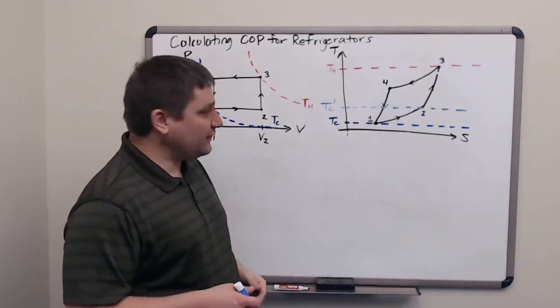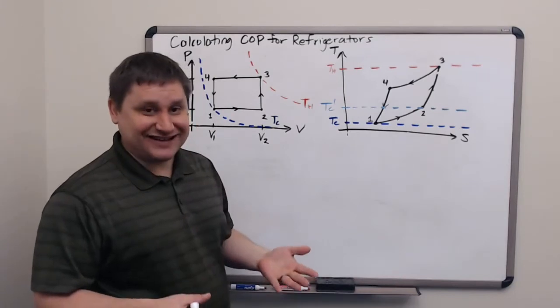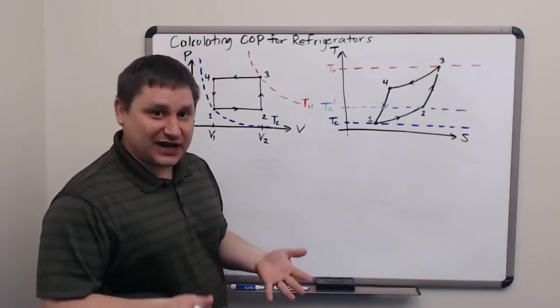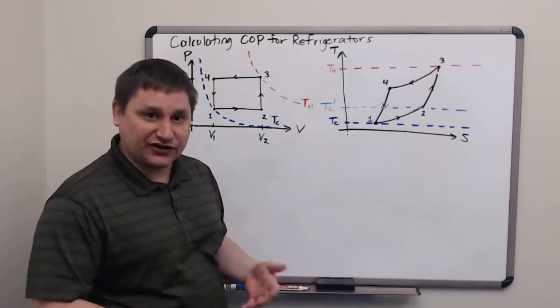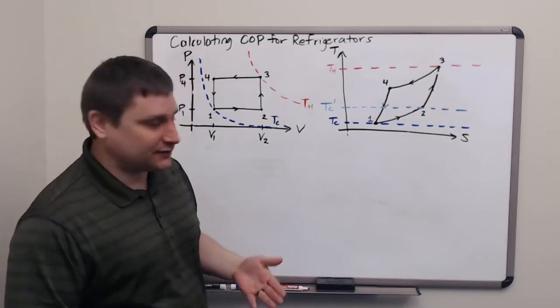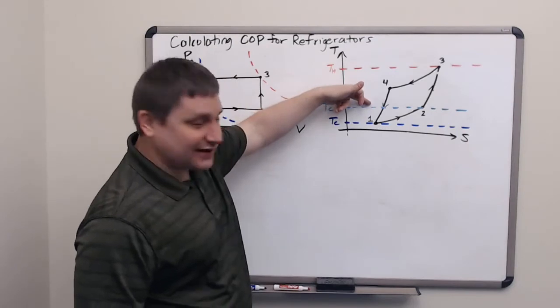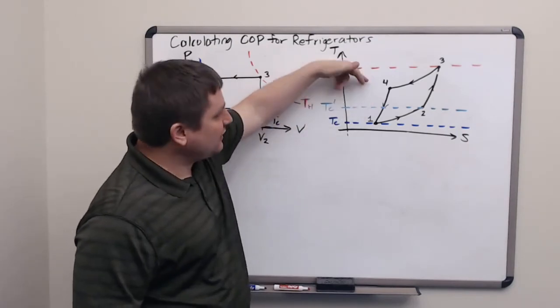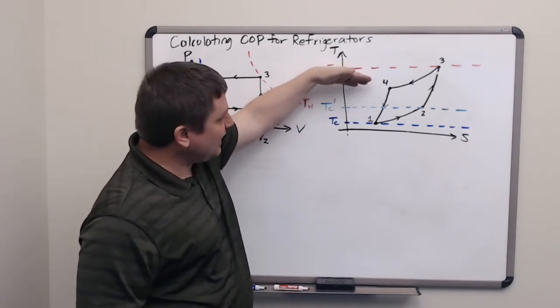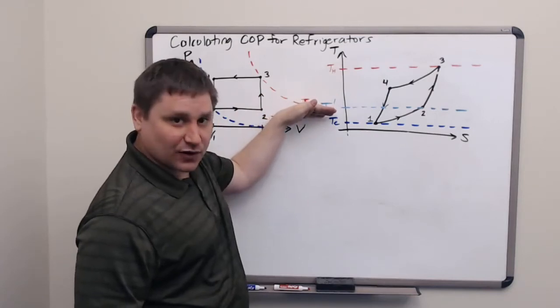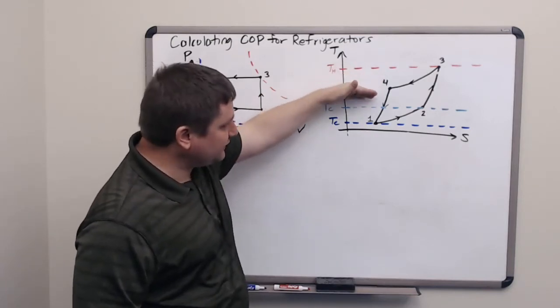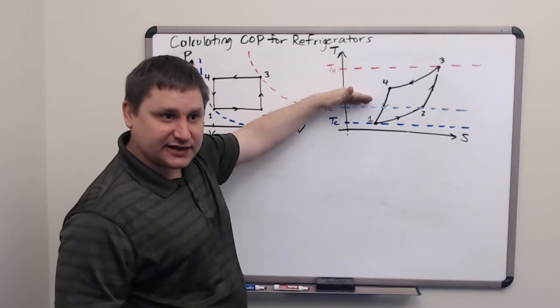Along 4 to 1, the entropy of the working substance is decreasing. Therefore, it must be ejecting heat to some reservoir which is colder than its current temperature. On the first half of this, that seems to be okay. The temperature of the substance is higher than the temperature of the reservoir, and so it can move to the left by ejecting heat.